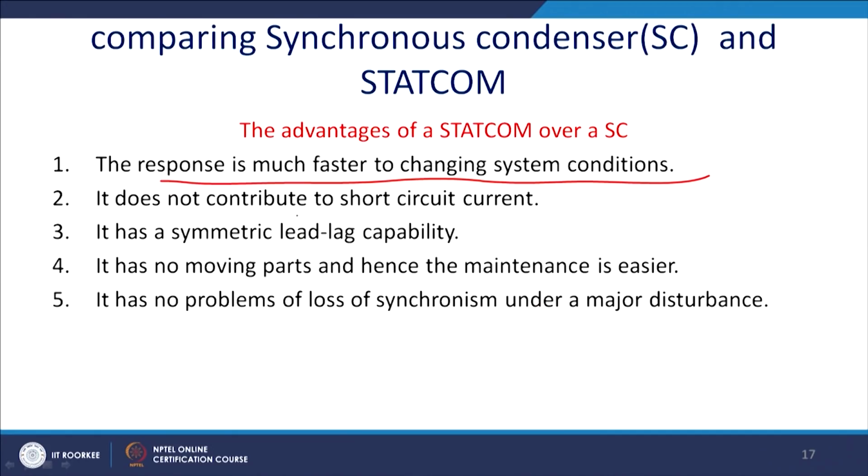It does not contribute to the short circuit current. It has a symmetric lead and lag capability, so both are symmetrical in nature. It has no moving parts, and thus maintenance is easier, and we can add redundancy by putting in extra legs or something like that, so that you have more reliability.